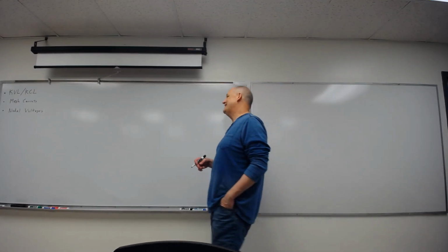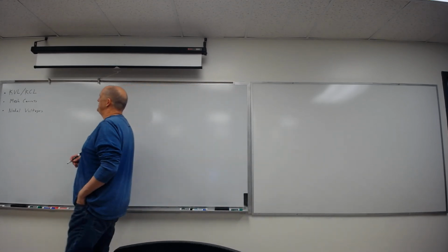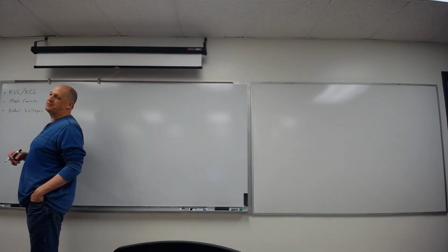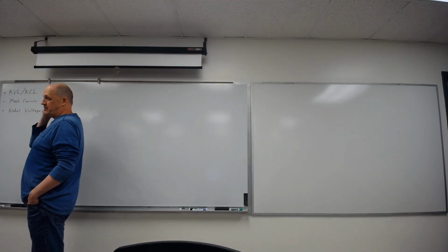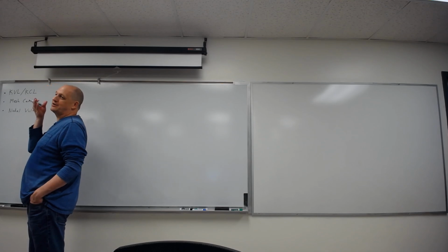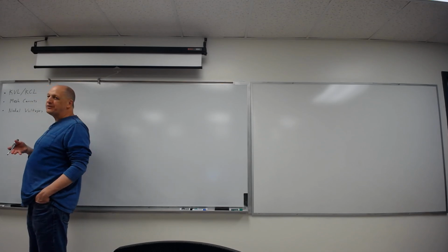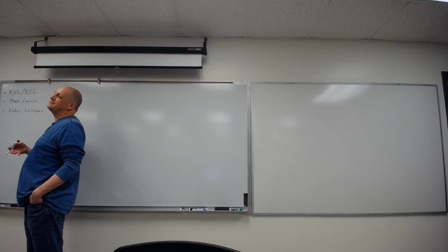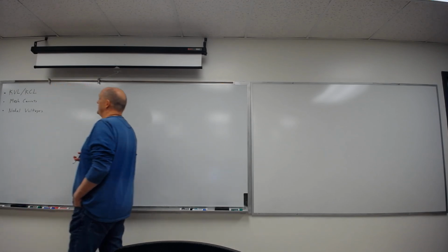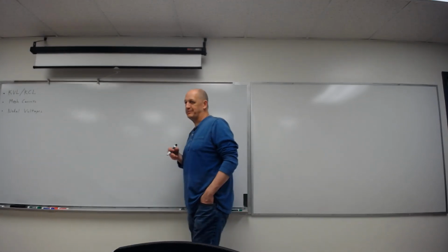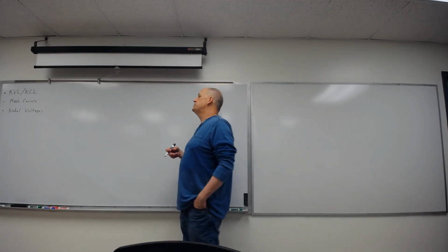Getting to know them is really just working through the problems, and usually you get a little bit of an indication. There'll be times with mesh currents where we need two current equations, or we can do one nodal voltage. But there are other times currents are a lot easier. With bridge circuits, currents are typically the easiest way to do it. So you should be able to use both.